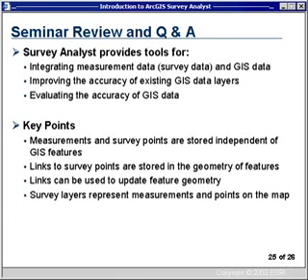How do I track which features have been adjusted by my survey data and which have not, so that I can manage the incremental improvement of my geodatabase? Your GIS features that have been adjusted by survey points will have links between the feature vertices and the survey points. The features that have not been adjusted by survey points will have no visible links between the vertices and the points. A question from Michael. Can Survey Analyst draw new features automatically from collected data? For example, if I shoot in 4 building corners and code them similarly, will Survey Analyst draw the building?